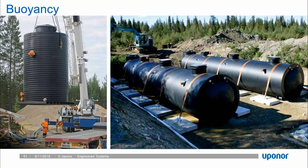But essentially, for both horizontal and vertical applications, we rely upon the soil load primarily to counteract buoyancy. For vertical applications, we expand the horizontal footprint of the base plate under the soil column to counteract the buoyant force. For horizontal applications, we create an anchor system that increases the surface area under the soil column. Soil weighs down those anchors and then counteracts buoyancy through the strap system. The weight of the vessel, the weight of concrete, the weight in general provides a very small contributing force downward to the overall buoyant force countermeasure.